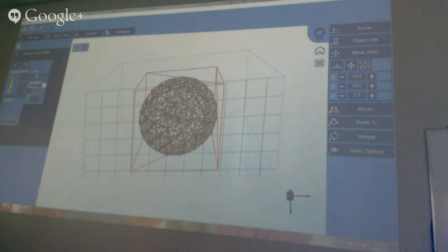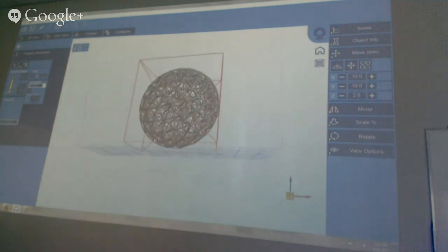I can show you the difference. Just looking at this, you can tell we need to add supports at the cross sections. But if we do it automatically, let's say this one, it has a gap of 5 millimeters.